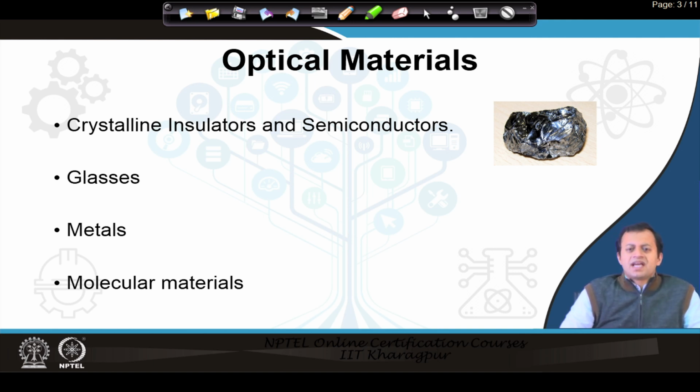So, the light can either get absorbed by changing the lattice vibration, or light can simply penetrate through the lattice spaces, or if the light is strong enough, say for example ultraviolet, it can get absorbed by the electrons of these crystalline insulators, even up to a point semiconductors like gallium nitride and gallium oxide, high band gap semiconductors. Ultraviolet light will be absorbed by them and the electron will go from the lower level to the upper level. Electronics engineering students will know, from valence band to conduction band.